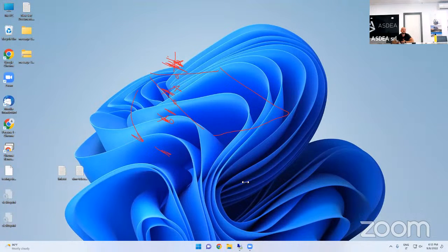Please, can you speak a little bit about rocking? Which consideration is necessary to model this type of connection? Well, rocking can be generated naturally if you want to use three-dimensional models, and in reality you have rocking because of the development of flexural cracks at the bottom. It can naturally be represented by a three-dimensional model, but then you talk about connections. So you want to model them as a lump nonlinearity.